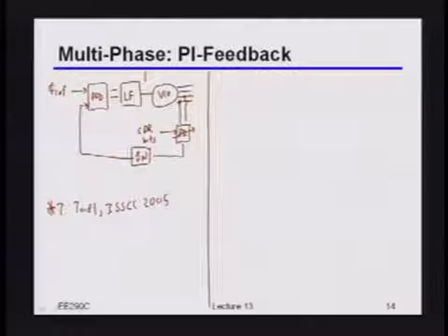So I mean, ideally the phase should be locked to like quadrature or something. Or depending on the lock point, you can probably change the, like, insert some offset into the comparison between the two phases. Okay, you could do that. Remember, I want a full 360 degrees of range, and I want to do that in a fairly transparent way, but you're absolutely right. I could just somehow muck with the phase frequency detector to adjust its offset.